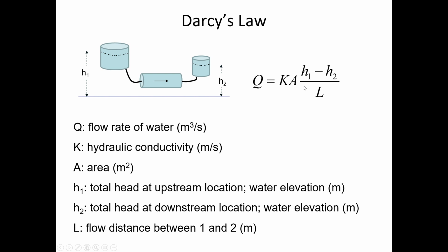So if we multiply the area by that gradient. The gradient is the driving force that's pushing. The whole reason why water's flowing through this pipe packed with soil is because of the elevation difference between the upstream and the downstream tank. So there's a proportionality factor, K. The hydraulic conductivity, which has units of length per time. Oftentimes you'd see it expressed in centimeters per day, but you could also express it in terms of meters per second. It's just going to be really, really small, particularly for something like clay. This proportionality factor describes how easily water can flow through a soil that's already saturated.